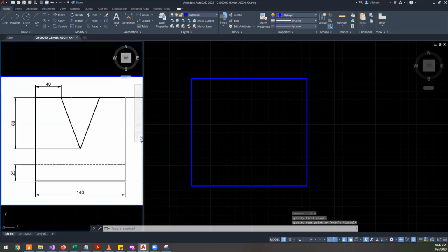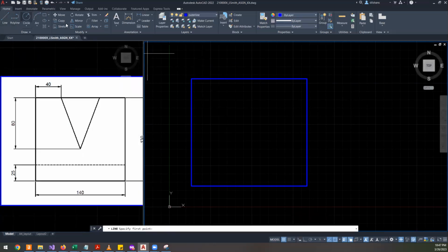So I saw some of you had done something like this. You click here and type @40,0, enter. Then you go like @30,-80. Something like this.